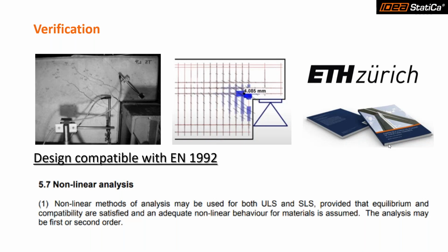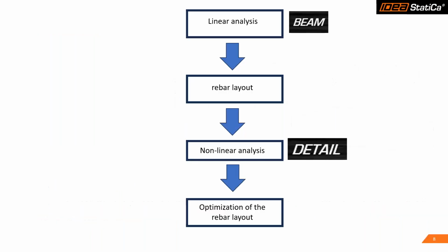I know that there are many engineers who for many years work elastic, and they're not experienced with nonlinear analysis, and then they ask this question. Is it allowed to calculate nonlinear? Yes, it is allowed, and for the European engineers, you can find paragraph 5.7 where you can see that it is allowed to calculate non-linear, but do not forget to take into account your national annexes, because there is different information from country to country referring to nonlinear analysis.